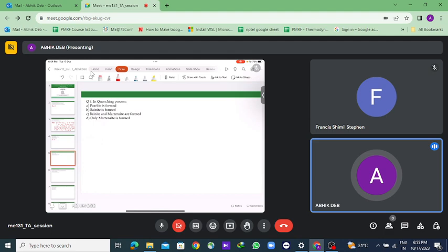Okay, we are decreasing the temperature. Then as martensite forms, martensite has a higher specific volume. This higher specific volume, that is the volume for a unit mass, is increasing. Since the volume is increasing, it will try to stretch out the regions. Due to this, on the surface there will be tensile stress generated. Since this is stretching out, the inner region will feel a compression from the outer region, that is from the surface region. So the inner region will have a compressive stress developed.